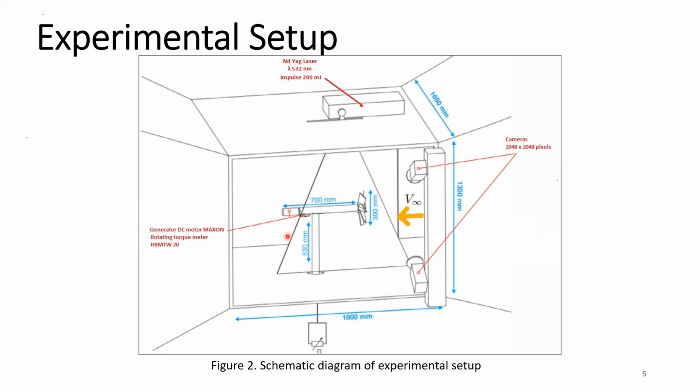The wind speed in the tunnel is kept approximately constant and is equal to 10 meters per second. The particle image velocimetry is handled by Dynamic Studio. The flow is continuously seeded with 2 to 5 micrometer diameter drops of oil sown by a fog machine. Approximately 200 double frame images have been acquired with each wind turbine mounted and operating at their optimum tip speed ratio. And these are the cameras which have captured 200 double frame images for both turbines.